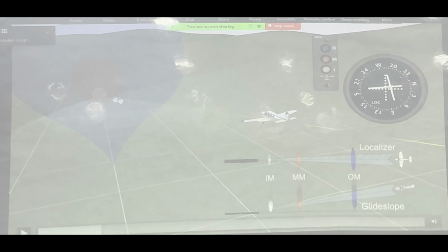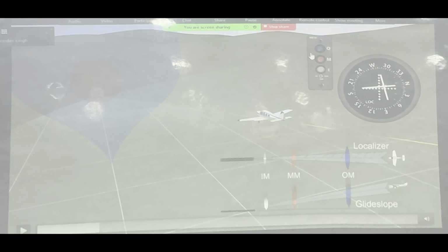The third thing is how far you are from touchdown. At that time technology was not that advanced. So what they used to have were directional transmitters, which used to transmit vertically up. Only once you are on top of the transmitter, you will hear that signal. You have lights in the cockpit, these 3 lights, and the audio also comes, so that you know how far you are from your aiming point, touchdown point.